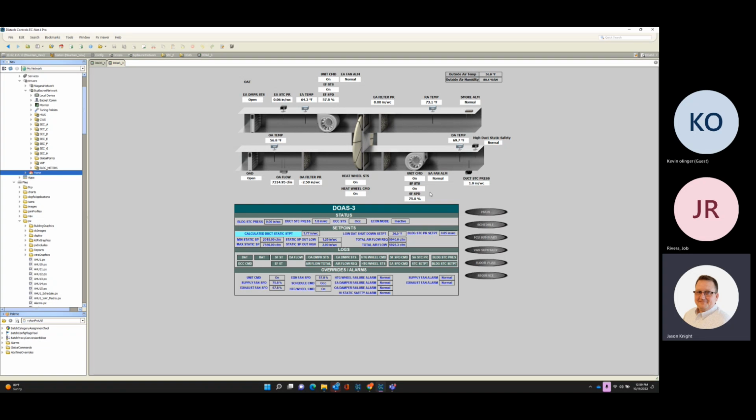Yeah, and depending on the unit, you know what I mean? If they only had fan coils that were available in a certain size, you've got some out there that are 3-speed: low, medium, high. Right, okay. So then your flow set points kind of go out the window. It's like, well, medium was close enough.